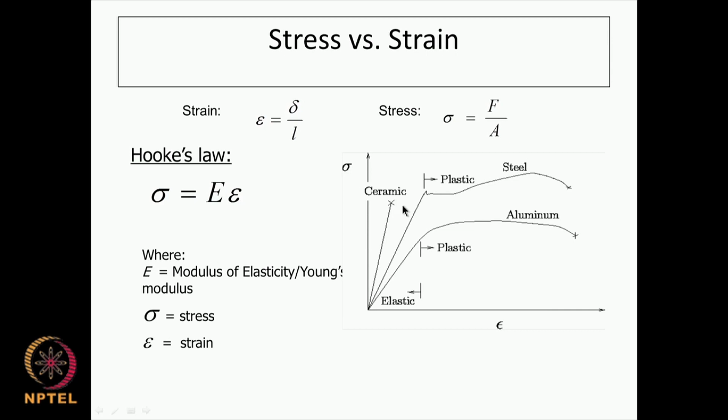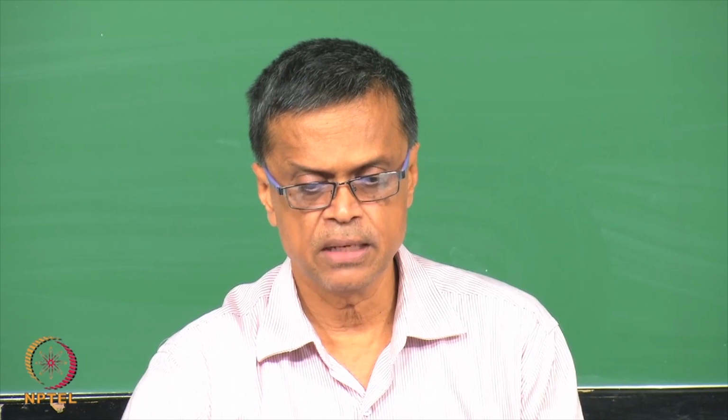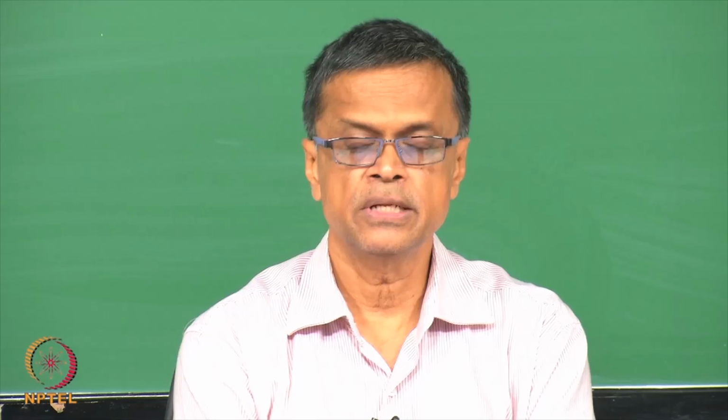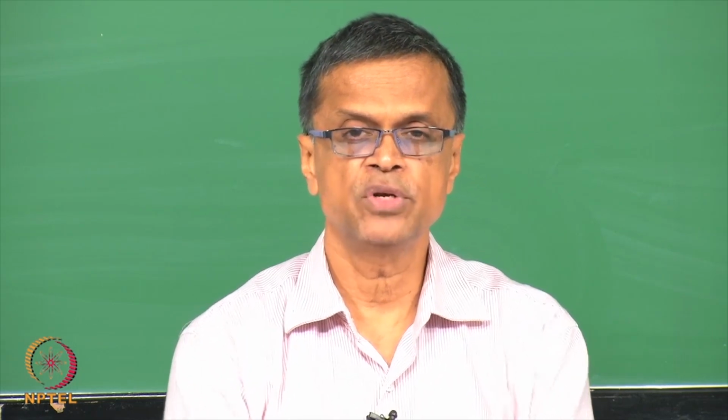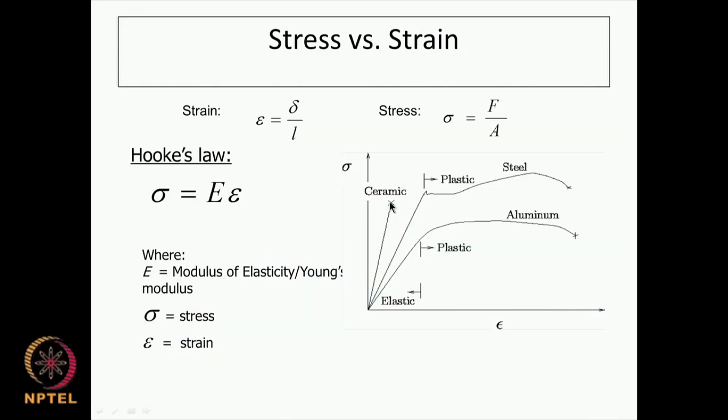That is the big problem with ceramics. They have very poor tensile strength. They cannot take much tensile force, and will just break. So if you have places where you need to have tension, like joints where tensile forces are acting, or compressive forces, especially in the foot region or in the leg, then ceramic is not a good material to use, because they do not go through elastic and plastic deformation as steel or aluminum can.